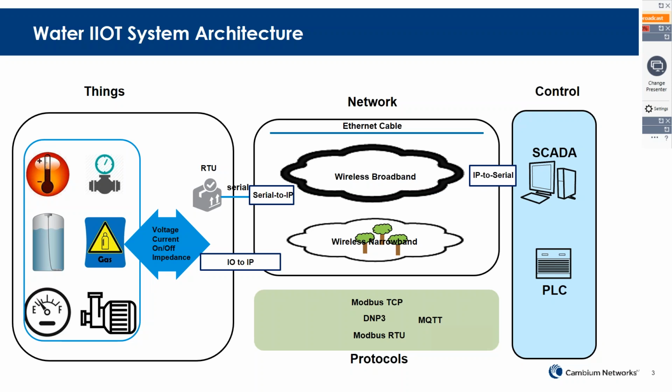And also, in the case of automatic control, like using a PLC, the PLC may make some smart decisions. For example, when you use Modbus TCP to query, it figures that the water level is too high. The PLC may send a command to this I/O to IP device to shut down the pump, or actually start pumping water out of the tank, depending on your setup.